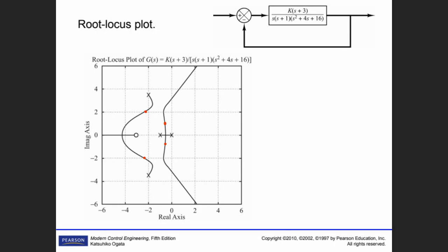Which one is more active or dominant? We have 4 poles. I select the K value, which I don't know, but it's giving us these 4 poles. Which one should I take into consideration? Which one can I neglect, in other words? Although this is not far away from origin.